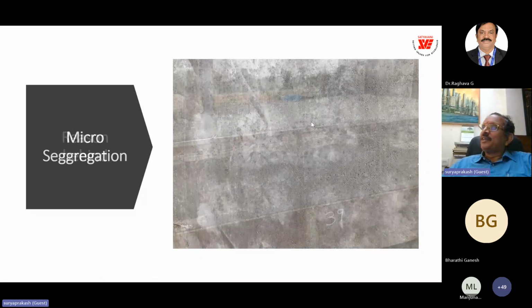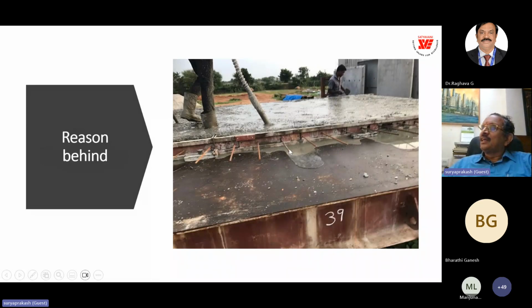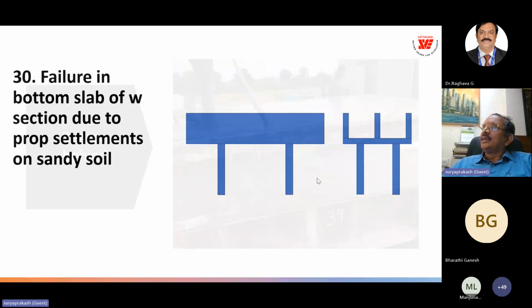So when we investigated, we found that there was excess water coming out when you are doing the compaction. Then I started verifying: design mix was okay, water cement ratio was very low, below 0.4. But at the actual site, when we checked, we found excess water. Then we found that the driver finally agreed that the mason asked for excess water, and he did that.